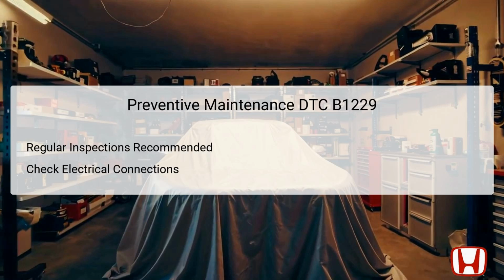In terms of preventive maintenance for the sunlight sensor circuit and associated components, it is advisable to conduct regular inspections as part of routine vehicle maintenance. Regularly checking the wiring and electrical connections can preemptively identify any signs of wear, corrosion, or loose connections that could later lead to DTC B1229.